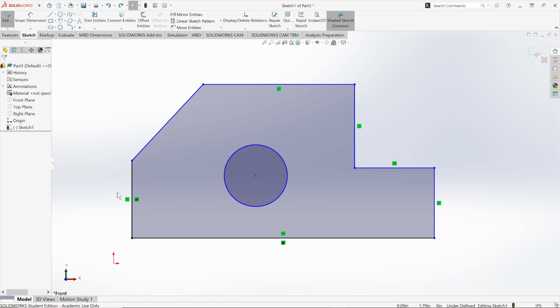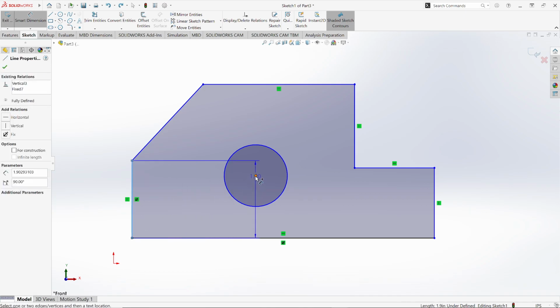I'm going to click off of it so you can see it was light blue, which was a highlighted element. So that means that I'm going to pull all the dimensions from these two lines that I can. I'm using these as my anchors, also known as baseline dimensioning. Basically these are set as datums, meaning all measurements to all the other feature edges should come from these datums. When I constrain this, I go to Smart Pick, and the first thing I do is I work my way inside and out. So I will select this datum going to that point,